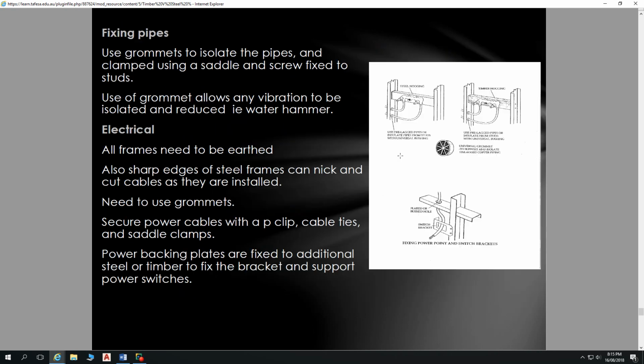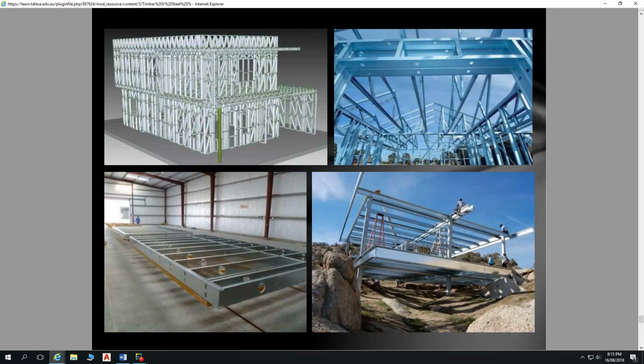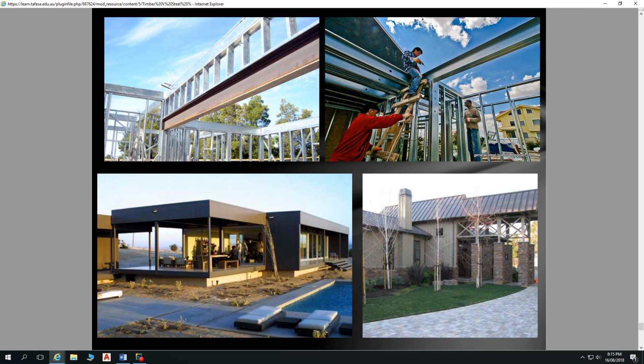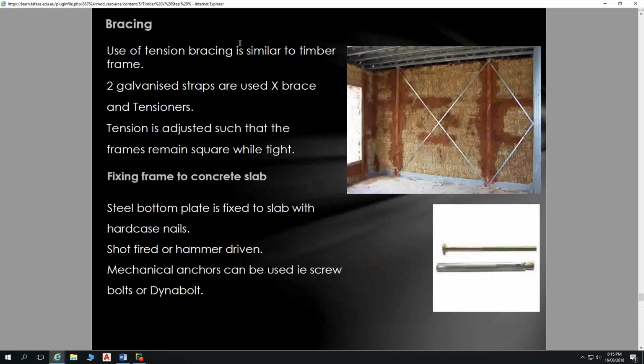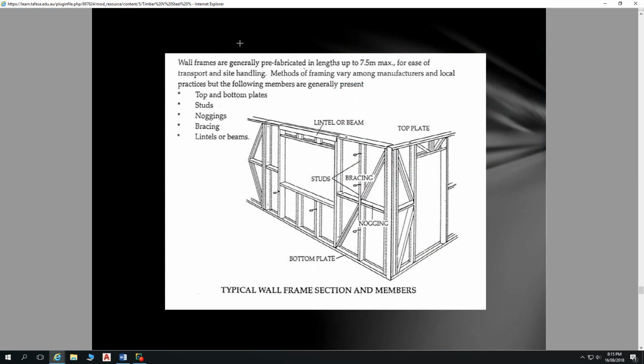And do we have any good pictures of some steel framing? Well, that's a fairly good one to illustrate that example. That steel frame, rather than that notion of thinking about studs, noggins, top plate, bottom plate, etc., is essentially a whole heap of trusses joined together. That's typically what we're seeing now in steel framing, because trusses work. They work as a single structural unit in and of themselves that incorporates its own bracing and sharing of loads between members.